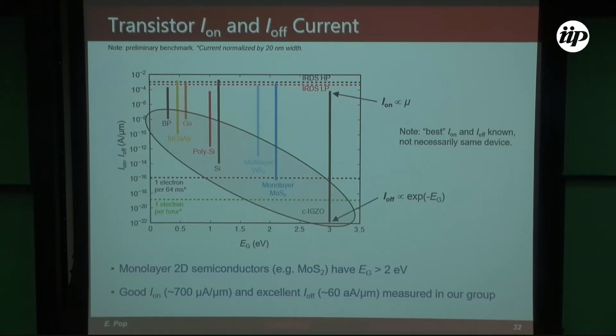And so, again, I don't have time to show the data, and truly speaking, this data is actually unpublished, but we've measured off-state currents. These off-state currents we haven't published yet, but we've measured them down in very special devices, very special structures. We've measured them to be down to about 60 attoamps per micron, which requires very special equipment and special devices to measure, but ultimately that's the fundamental limit down here somewhere, because it's going to have to scale with the larger band gap of the material.